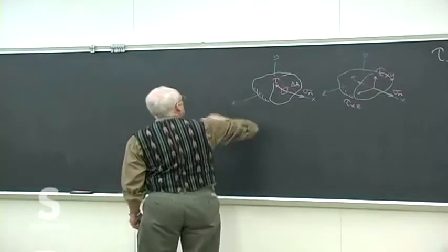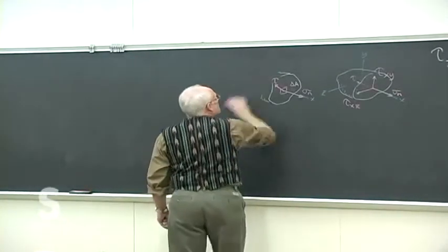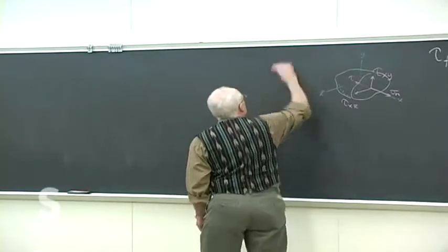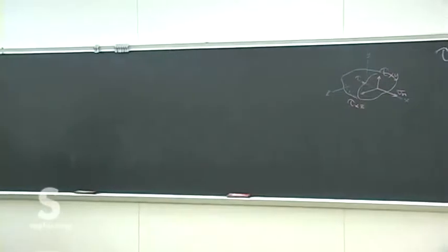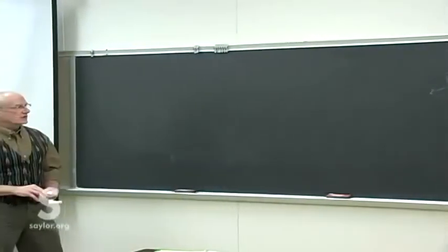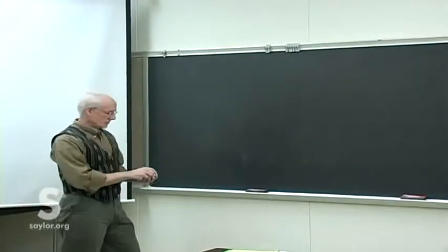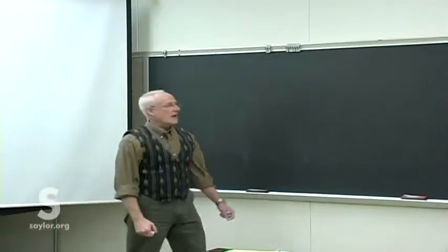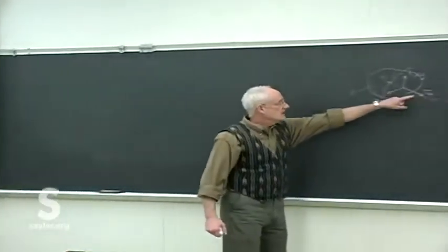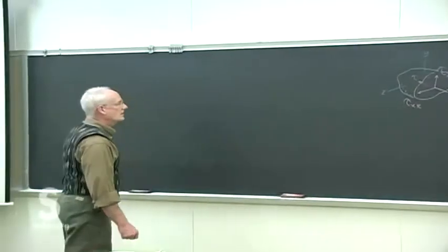So no matter what my loading is, no matter where I actually have this cut, we can resolve the resultant force, calculate the resulting stresses, both normal and shear, and draw them with that kind of designation. Remember, the actual directions of these are arbitrary. I had to draw something, so I just happened to draw them all in that direction.